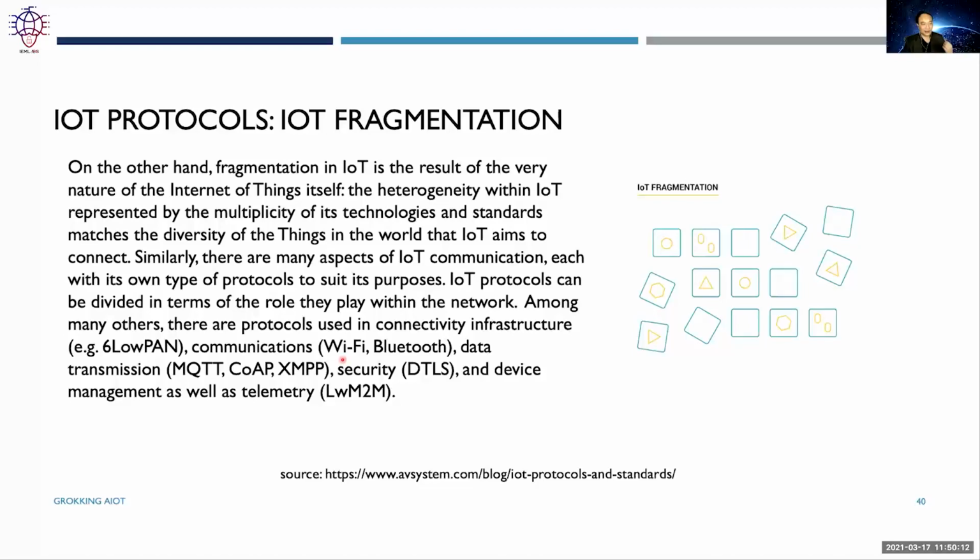that, some 802.15.4 packet radio. This is a small machine-to-machine transmission network that's actually being defined by the IEEE. It's like Wi-Fi, but it's meant for much lower speed, shorter range, and lower power. So there's this kind of technology, and that is actually being adopted by things like Zigbee.